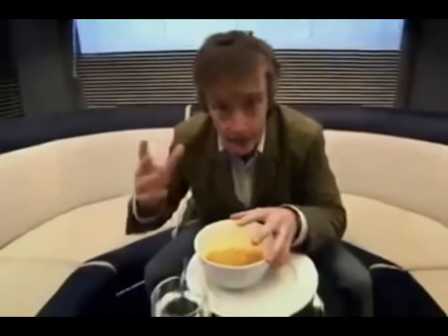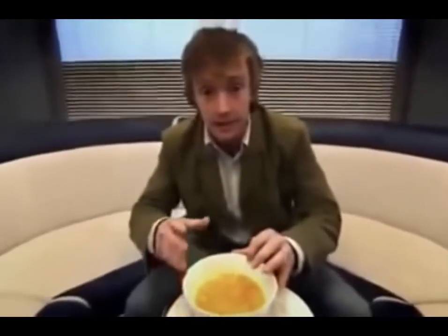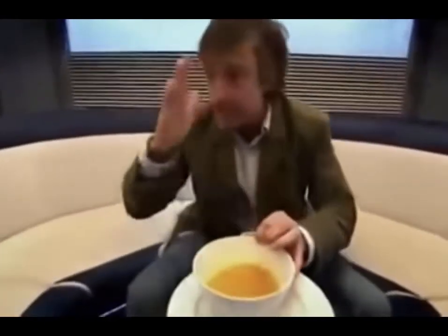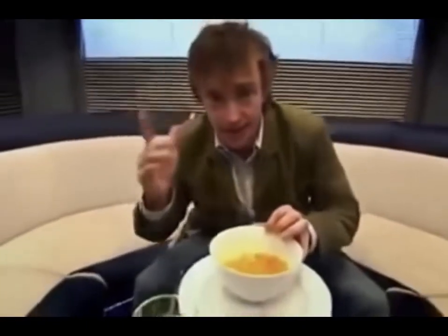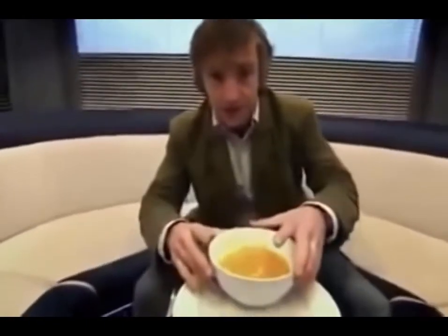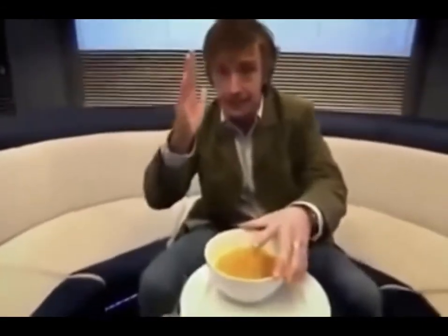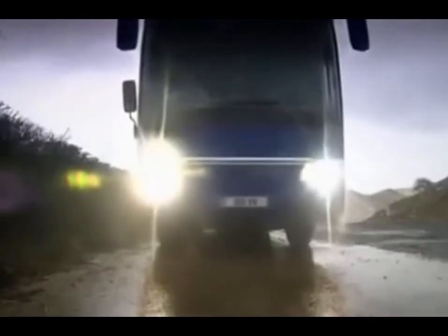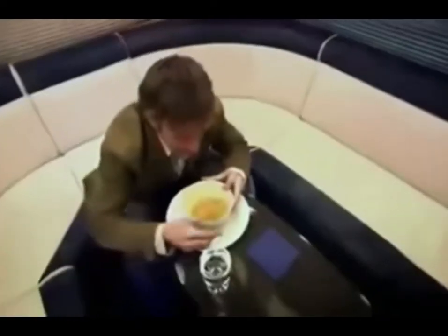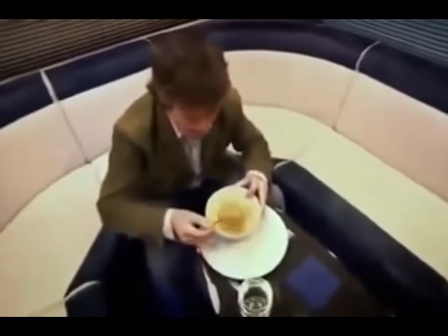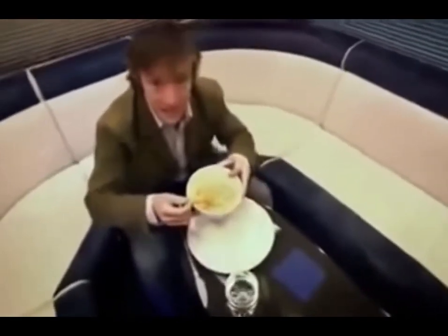Before Taipei 101 was built, it had to overcome the problem all flexible buildings face, swaying back and forth in high winds. And like any structure, it has a natural frequency. In this case, one complete cycle of swaying motion from here to here and back again takes about 7 seconds. Now, for customers in the restaurant, that would be like sitting on board a bus that every 3.5 seconds accelerates and then brakes. And that's the delicate problem I'm talking about. At the top of the Taipei Tower in a typhoon, you wouldn't just spill your soup, you'd probably see your whole lunch again.